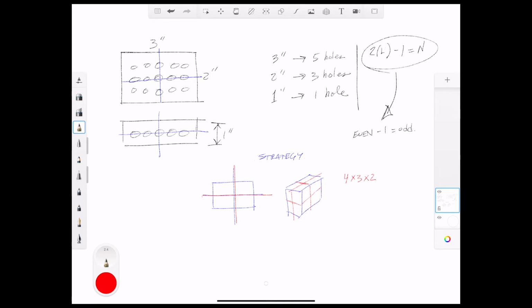So I will start with the 4 inches and the 3 inches, and then I will extrude it backwards 2 inches. Then I will go ahead and pop into my part a center circle, and I will do that center circle and then put a chamfer on that circle.